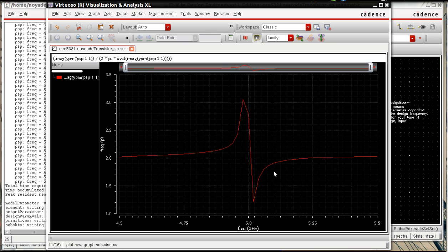In this case, we see that the capacitance is actually quite different with a large signal perturbation than it was with a small perturbation. The small perturbation showed a capacitance of approximately 900 femtofarads, whereas the large perturbation shows a capacitance of approximately 2 picofarads. Don't be concerned with this large spike in the middle. This is due to the perturbation source disrupting the admittance around this frequency, but you can see that the average value is somewhere around 2 picofarads.